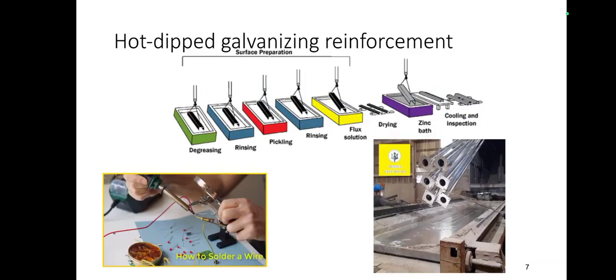And the next one is hot dip galvanizing. This is a process we might have seen in many electrical poles. If you do normal painting with zinc, you know about zinc primer and all, what will happen is, if you paint manually, we can see some pores will be visible, and thereby corrosion will try to initiate.